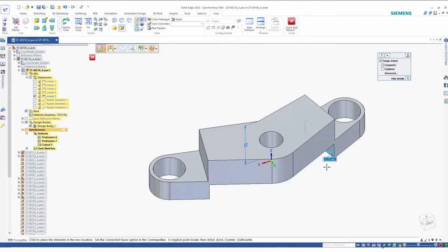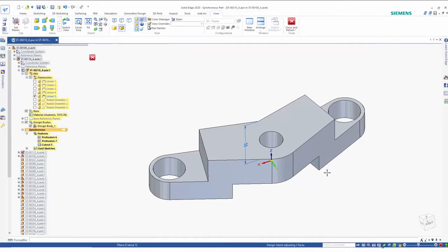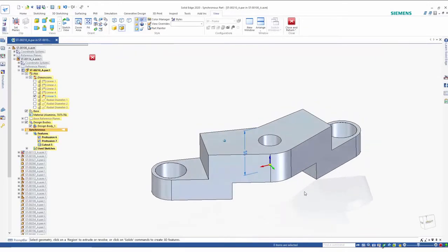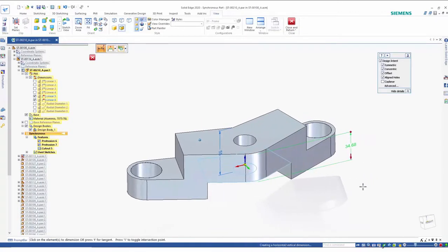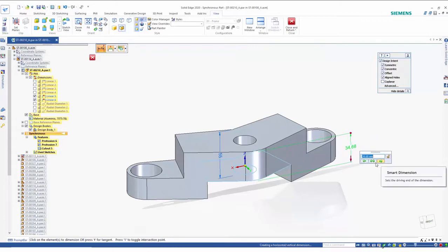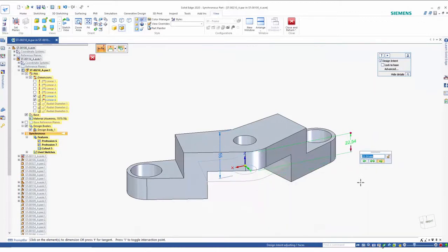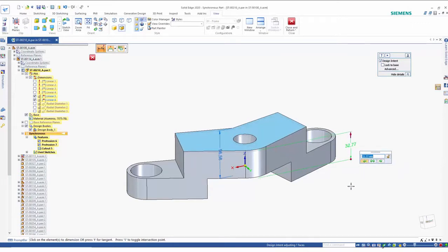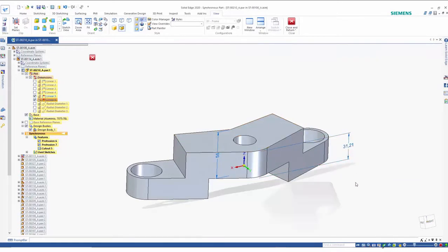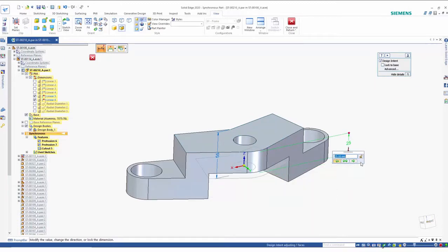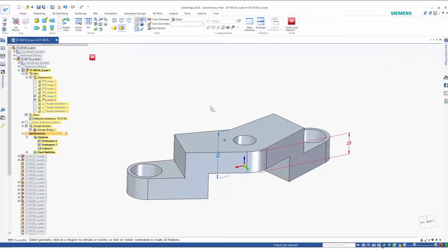Most 3D CAD systems require you to carefully plan the design steps so that edits can be made later. Using synchronous technology, we can create geometry in the most convenient manner, but have total flexibility in altering the intent later. 3D driving dimensions can be added at any time to simply edit or lock a design feature into shape. Again, notice the PMI drives the model and gives the designer the flexibility to specify exactly how the change will be made, something sketch dimensions don't allow for. The benefit here is that you have flexible designs without having to plan for them.